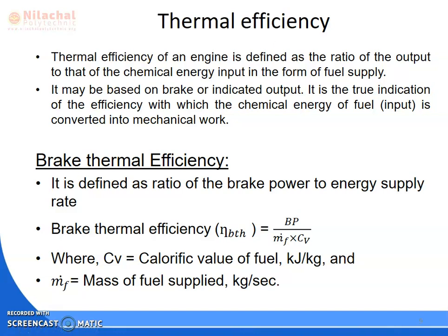the ratio of net work done to heat supply. So in the case of an IC engine, what is your output? Output is your power. It may be indicated power, it may be brake power. And what is your input? Input is your fuel supply. So likewise we are calculating your thermal efficiency.